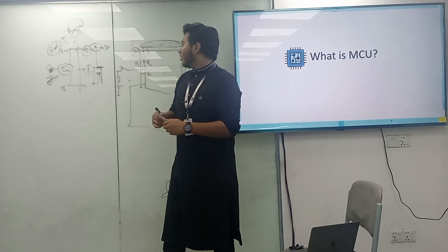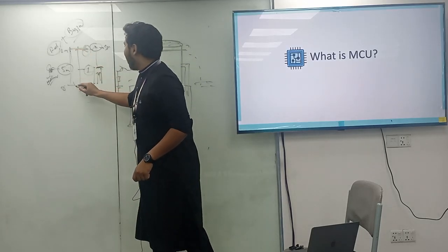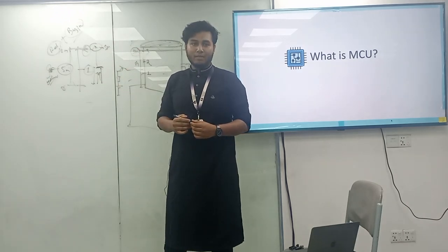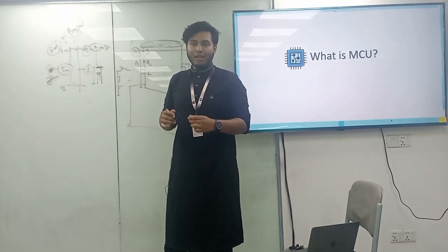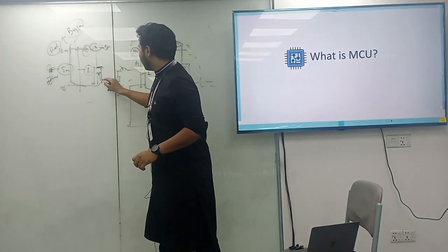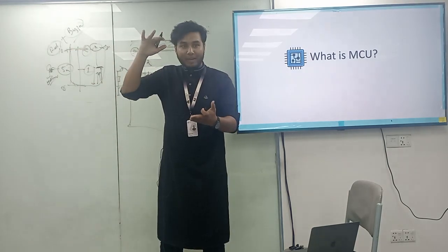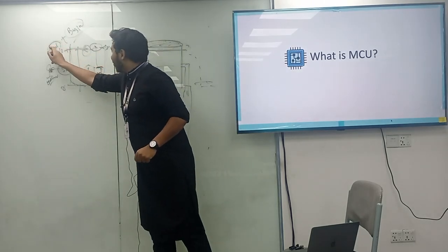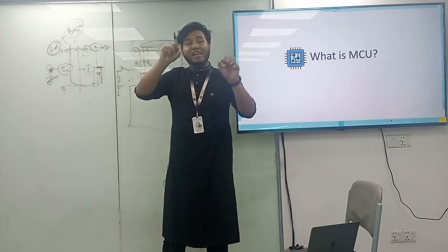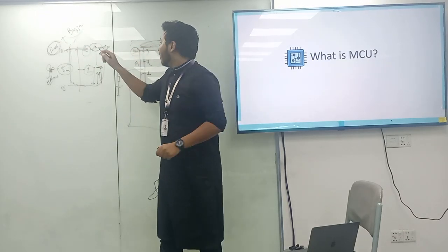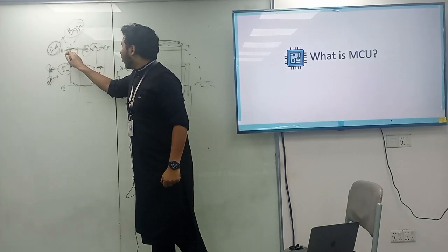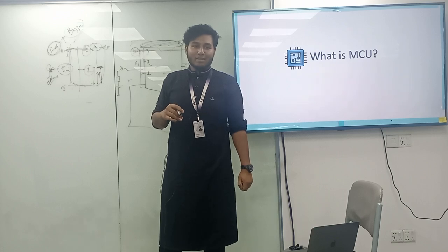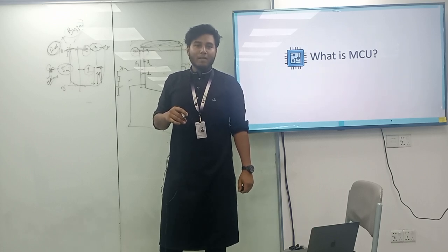Now a question to you: if the tank is 10 meters in height, will you set your indicator to 10 meters or less than that? If your tank is 10 meters in total height, and you want to fill the tank, and you want to put that red light with the buzzer to set an alarm, an indicator, are you going to set that indicator at 10 meters or lower than that? Or slightly lower than that? Almost full, sir. Almost full.